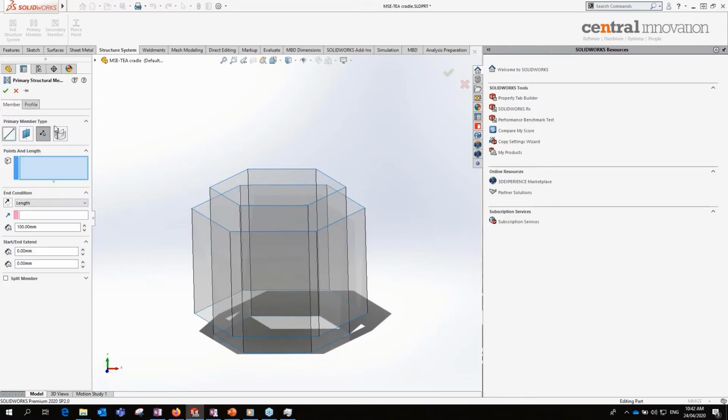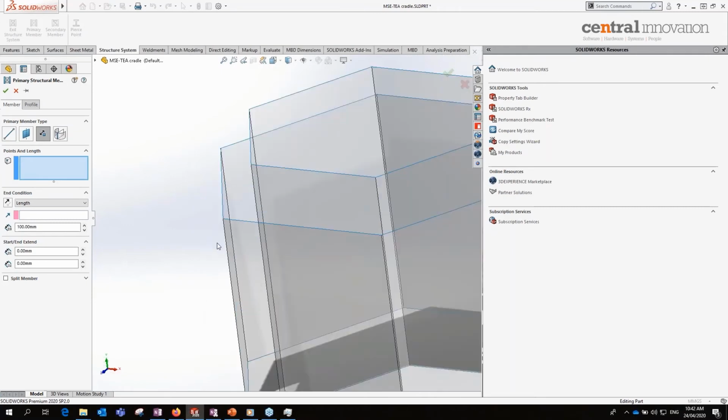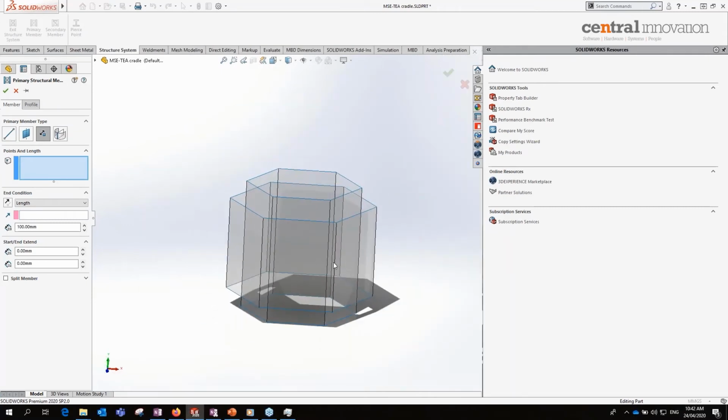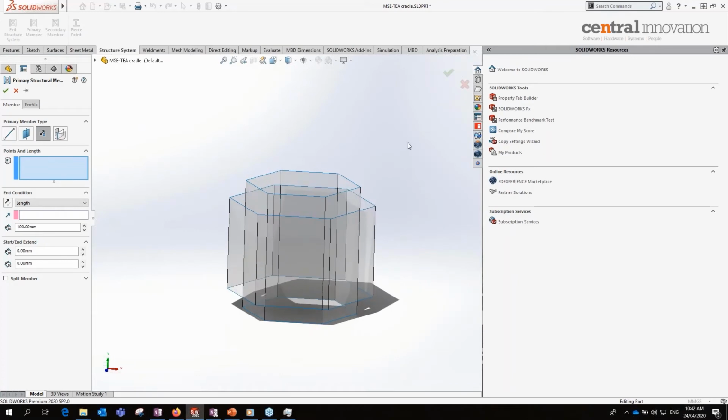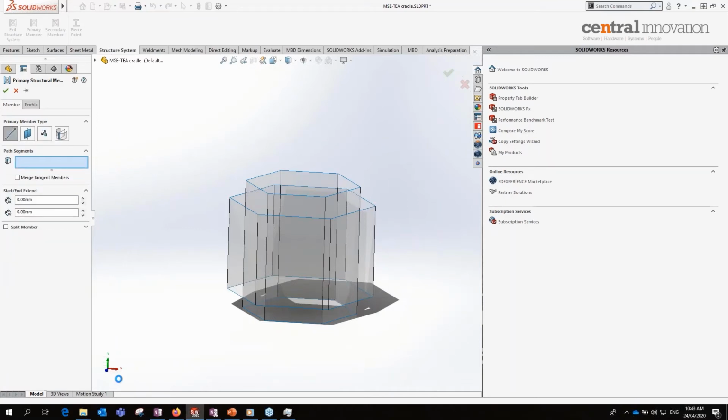All right. So I want to create a tube square for all of the edges of the surfaces, even the intersecting edge, not only the end edges, all the edges of the surface. So all you have to do is just window select. But before I do the window select, I have to make sure first that I'm using the proper options, that pass segment or member.